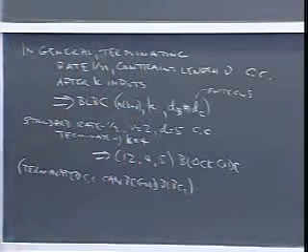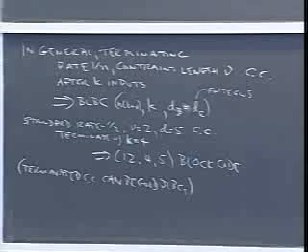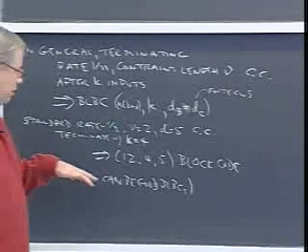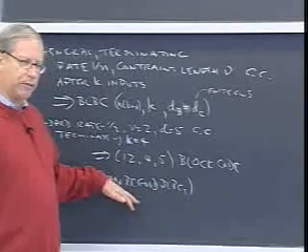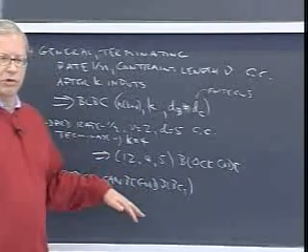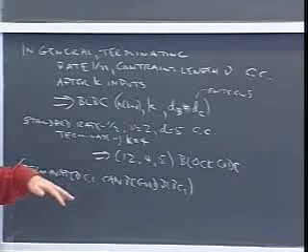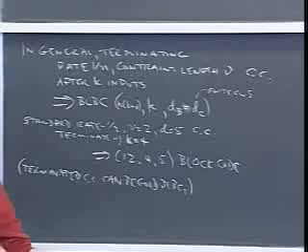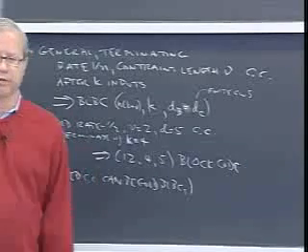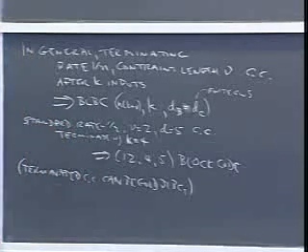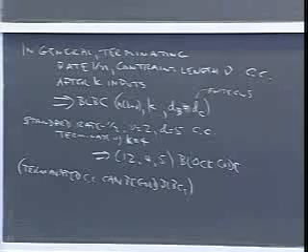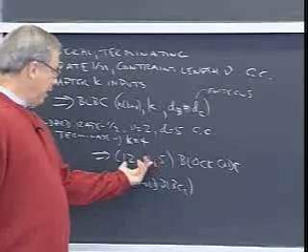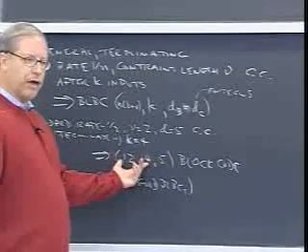And in fact, asymptotically, by choosing the parameters correctly, you can show that you can get a random ensemble of terminated convolutional codes that is as good as the best possible random ensemble of block codes. So terminated convolutional codes is one way of constructing optimal block codes in the asymptotic limit. These parameters aren't bad. Here's a rate 1/3 code with distance 5, not too long.